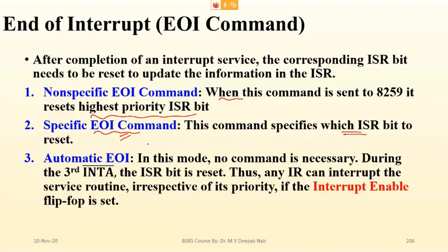Automatic end of interrupt. If we are using the device in automatic end of interrupt mode, then no command is necessary. You don't have to pass either the specific or non-specific end of interrupt commands. That means the 8085 does not have to send any end of interrupt command. It will be done automatically. How? During the third INTA.